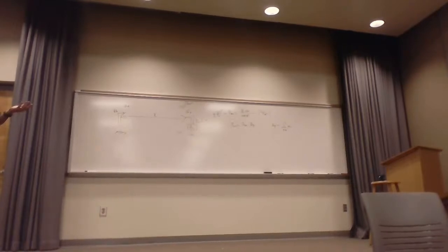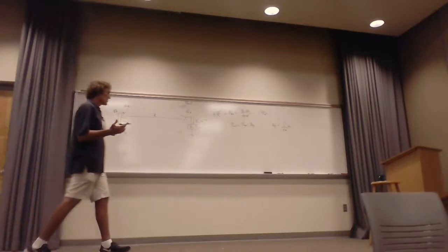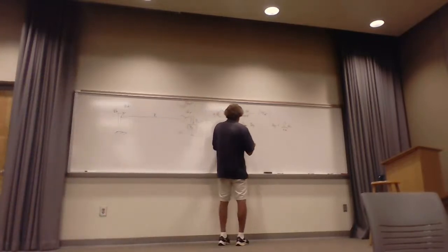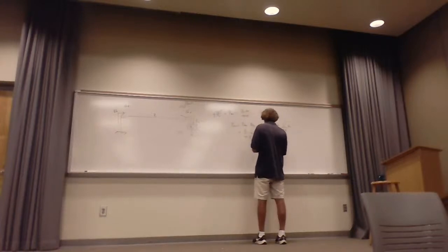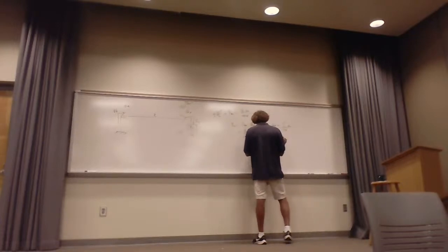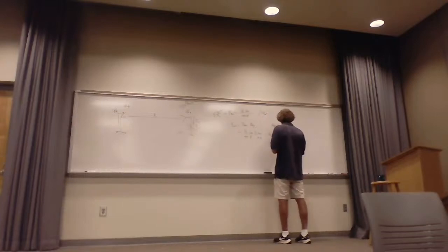In other words, there's nothing you don't know. So this is the average power, I mean, this is the P received. If you want to, you can put the whole 9 yards in here. You can put P transmitter over 4 pi, then you can put R squared right there times gain transmitter, then times lambda squared gain receiver over 4 pi. And lo and behold, when you do the whole 9 yards, it's transmitter power, and then it's going to be times lambda over 4 pi R squared, right? Times gain transmitter, gain receiver.